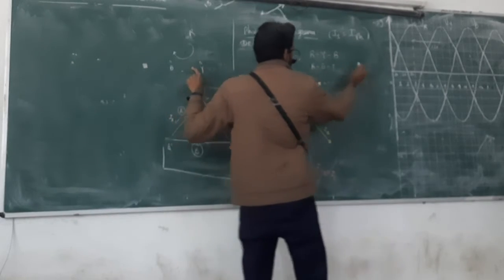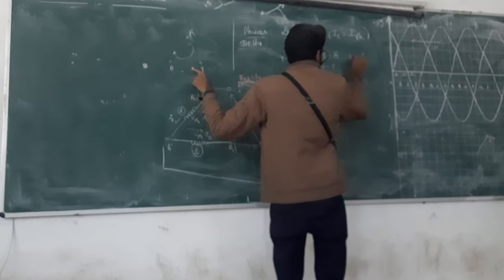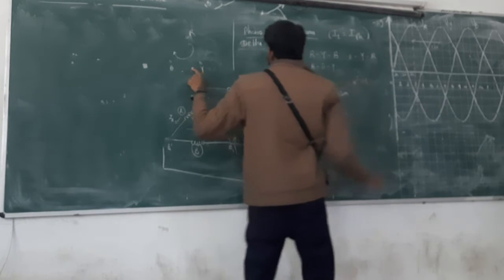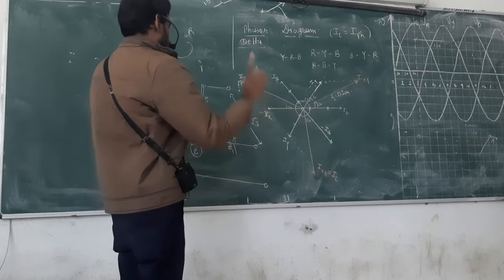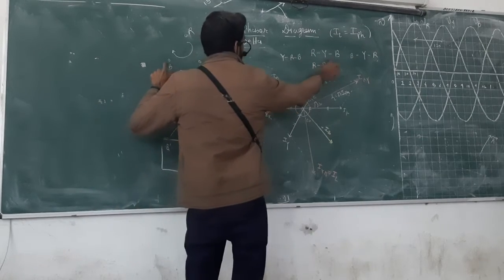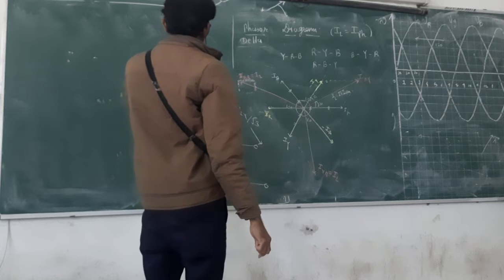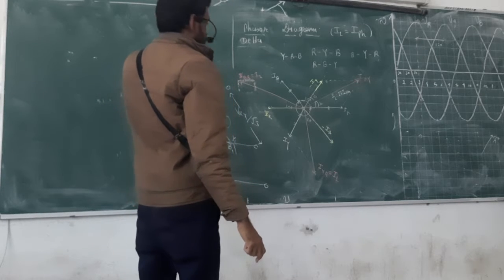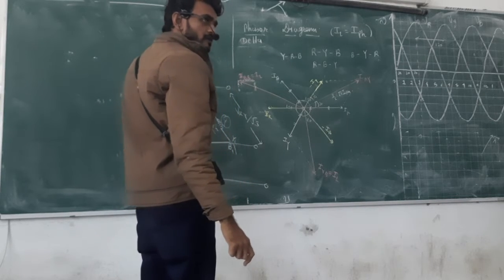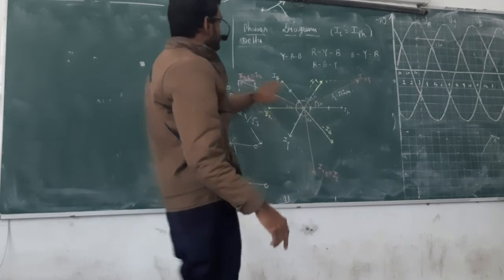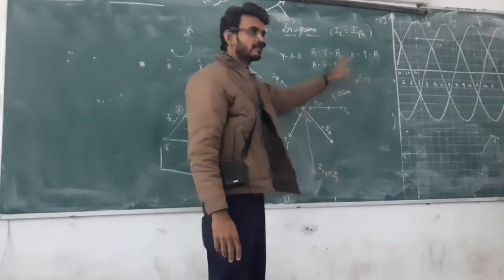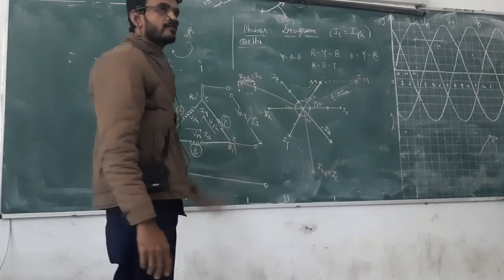Interchange these two: B, Y, R. So you interchange any two letters of R, Y, B, and the rotating pattern will be changed.